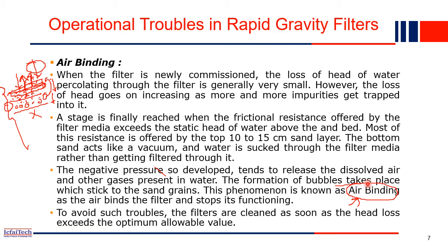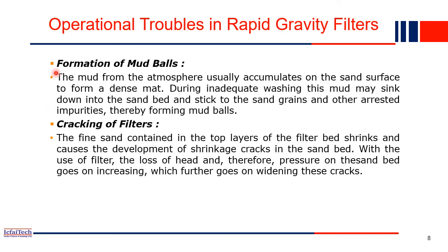To avoid this type of air binding, we have to clean the filter medium frequently, every day, or maybe every alternate day or every week, through backwashing. We have to clean it so that no air bubbles form inside the filter. Now the next problem you will find is the formation of mud balls.